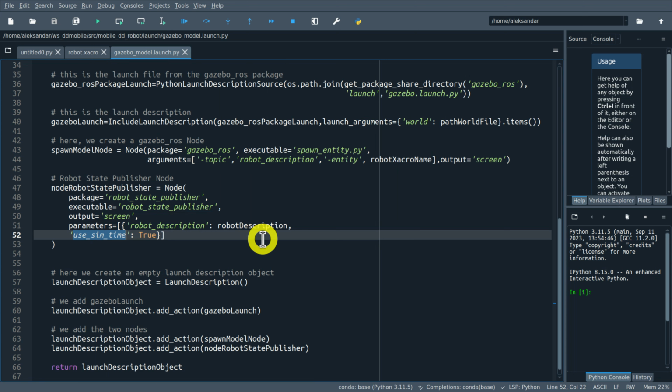Here they are. Let's align everything, that looks fine. And let's save this file. Okay, so this was the first step. Now we have all the dependencies. Then we need to adjust the CMakeLists.txt file. We need to tell ROS2 that important files are stored in the two new folders, launch and model. That is, these are the two new folders we created, and currently ROS doesn't know that there are some important files in these two folders. So let's do that.